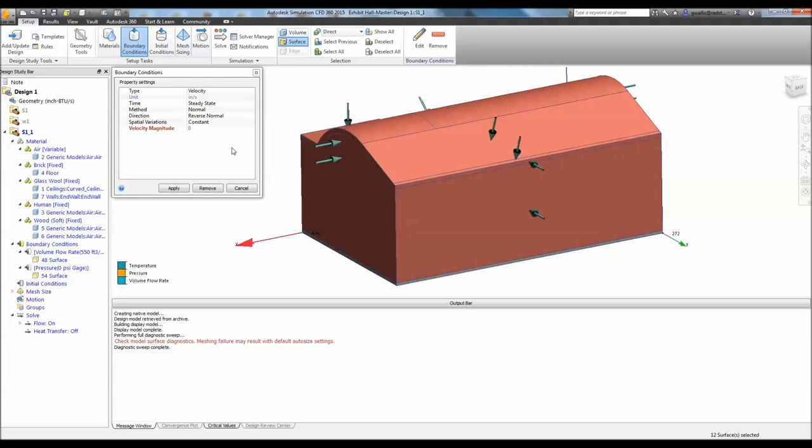So we're simulating that the outside temperature is quite warm, and we want to determine the film coefficient here. It is a setting that we need to select. In the type here, we can actually choose that condition. As I scroll down here, you can see film coefficient. We can then apply the value or the unit.